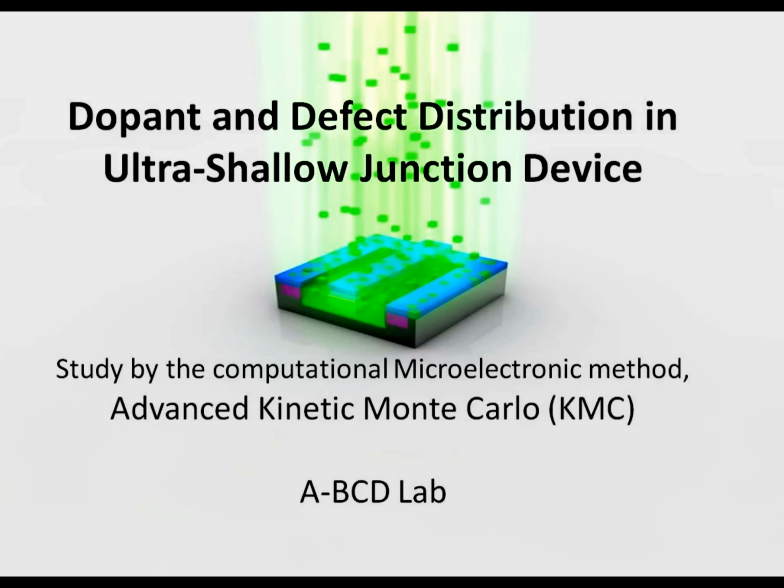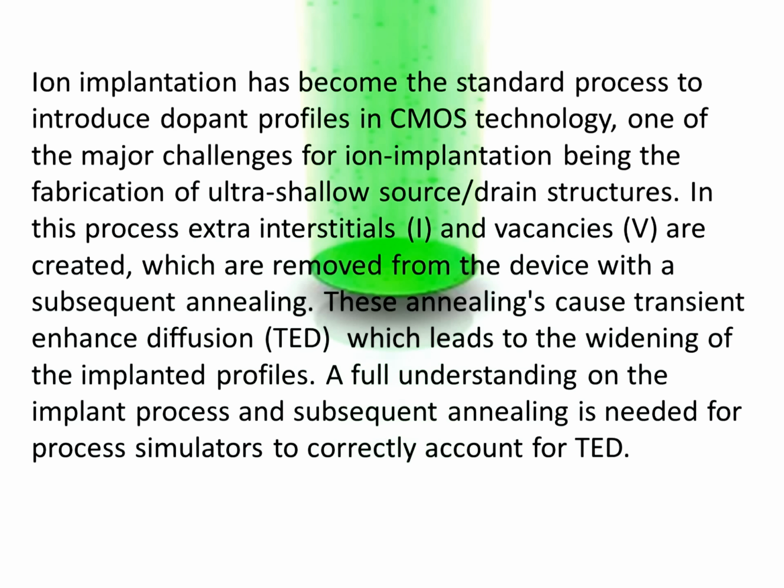Dopant and defect distribution in ultra-shallow junction device study by the Computational Micro-Electronics Method Advanced Kinetic Monte Carlo. Ion implantation has become the standard process to introduce dopant profiles in CMOS technology. One of the major challenges for ion implantation is the fabrication of ultra-shallow source drain structures.